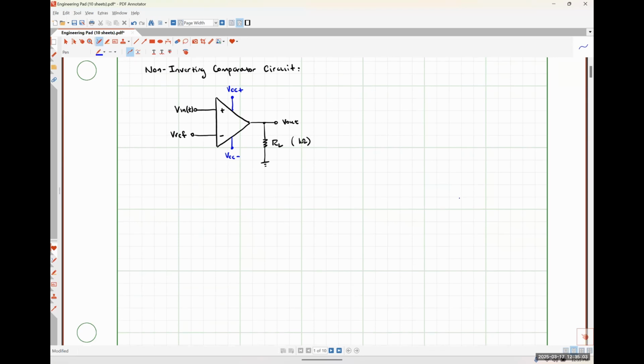If we were to represent this particular circuit using the practical op amp model, we would have something akin to this. Let me start here. Here's my input resistance. This is going to be my differential voltage VD, making this my non-inverting input terminal, and this my inverting input terminal. On this side, I would have that dependent source, where I will have my open loop gain, AVOL, multiplied by my differential voltage VD. Here is my output resistance, Rout, and my ground bus down here.